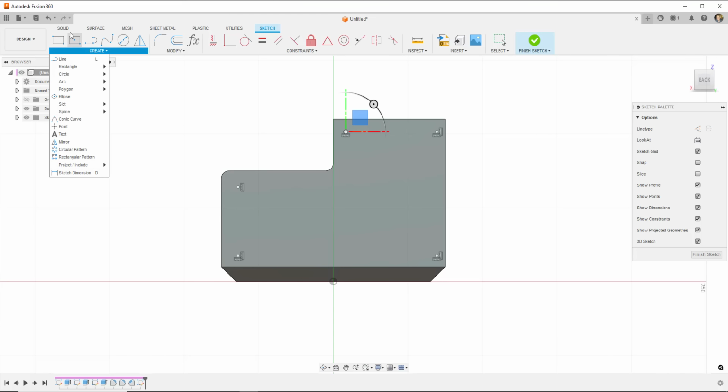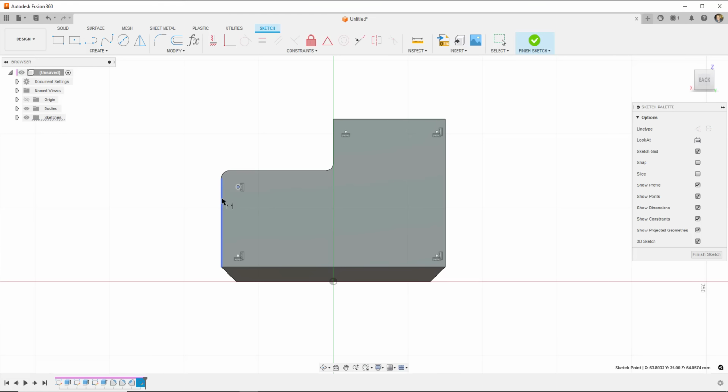I'm going to go under create to sketch dimension, and lay them out with some dimensions. So we click the point and we click the edge, okay, and let's go with 12, and you might notice both of these moved, because when we drew them, remember we've got those extended lines, it aligned them up with each other. If I show you that again, on here, if I go 12, only that one will move, but on here, if I select those 2 points and type in 12, both of these moved because again it's aligned.